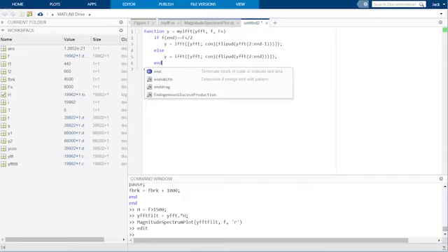As the speech in the audio file says, the Fourier transform of a real-valued signal is conjugate symmetric. That is, the tail of the Fourier transform is the mirrored complex conjugate of the front of the Fourier transform for real-valued signals. So for real-valued signals, these entries provide no additional information.